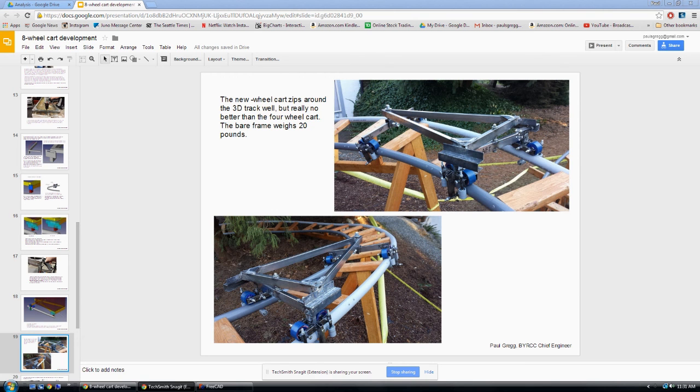The other nice thing about this system in the back is that this 5/16 bolt here that's pivoting really doesn't do the heavy work. The heavy load is taken through the bearings on the very end. And when you have a moment you have to react, the further apart those reaction points are, the less the local loads are going to be. So I'm not stressing some small bolt too much here in the middle.